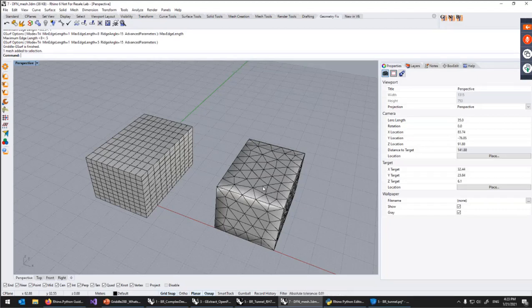Or if you want to have structured mesh, you can directly work on polysurfaces or solids represented by BREP objects. But the opposite is not possible. Well, technically you can create analytical objects by approximating surface meshes, because a surface mesh is essentially a discrete representation of some surface.